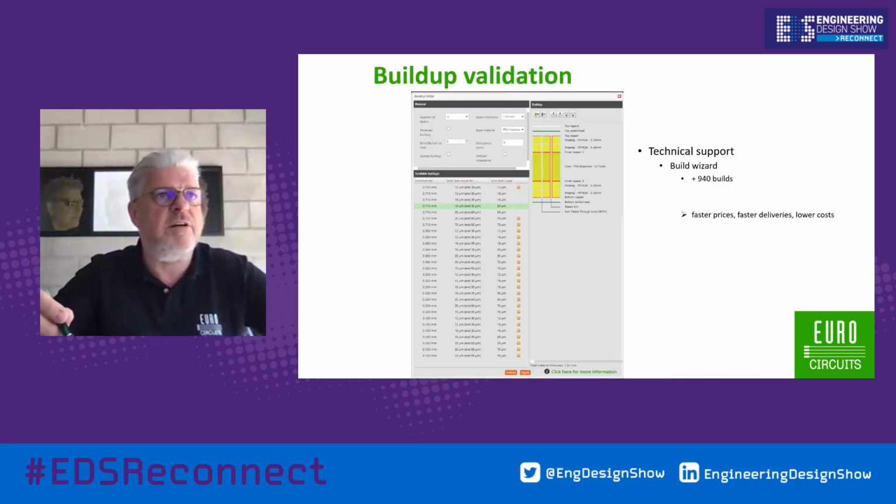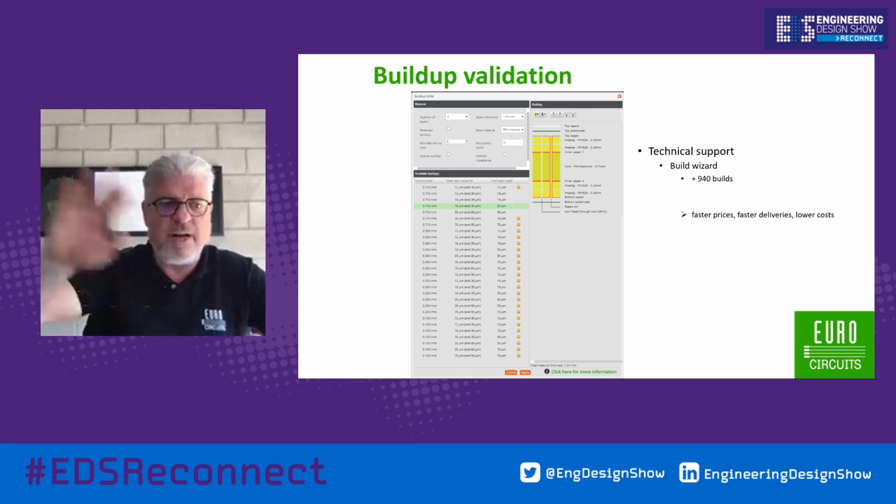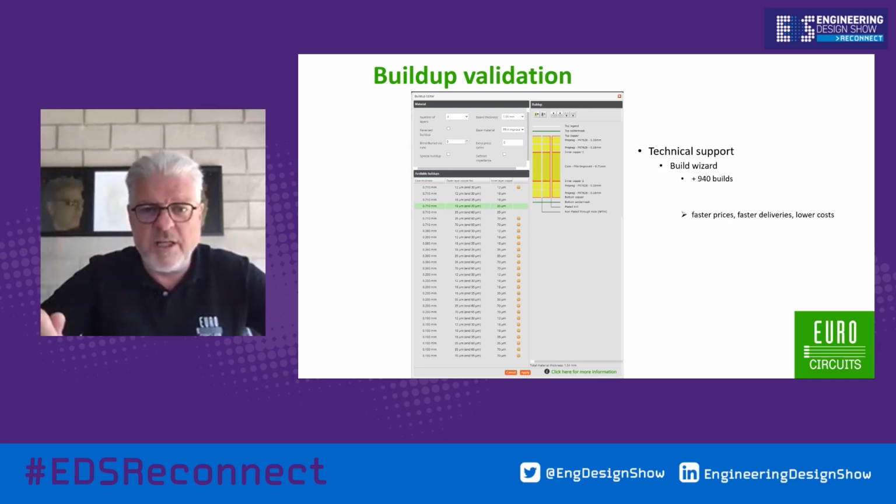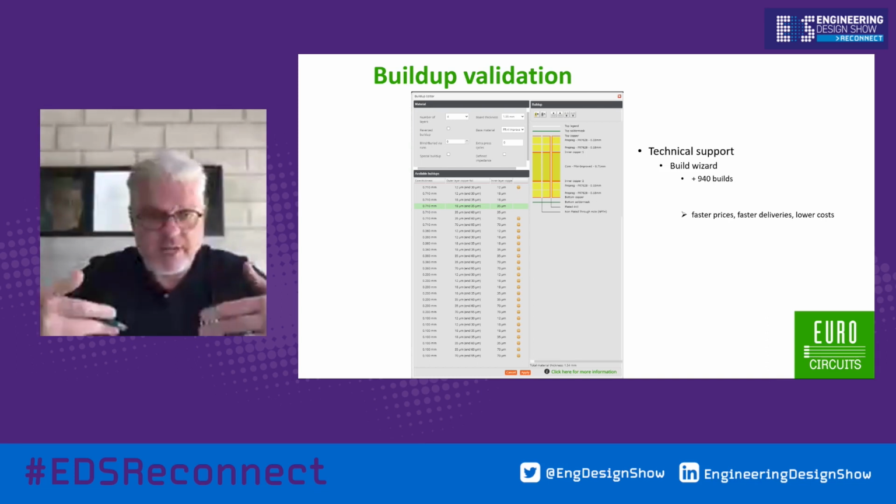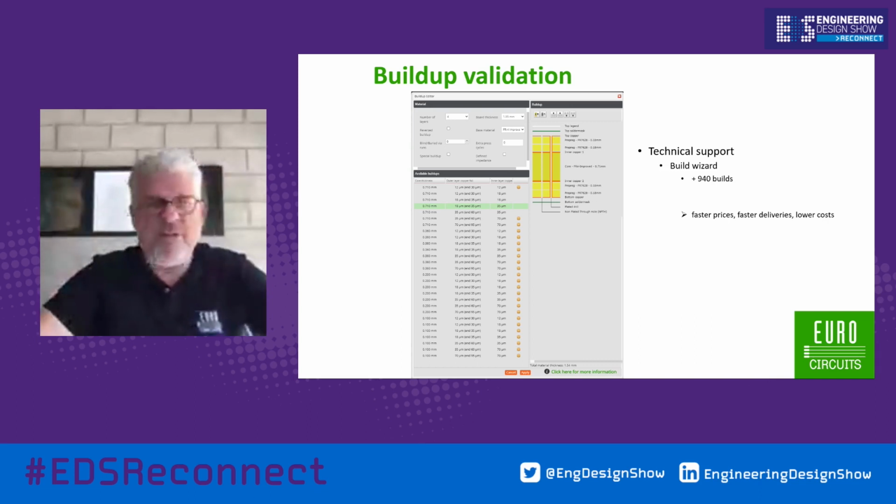To give you a nice example is build-up. Build-up or stack-up is one of the most critical things to choose from. If you start building your own stack-up to your own liking, from what you can find on the internet for materials, then you're not sure if they are available, if your manufacturer likes to work with them, how long it will take for your manufacturer to get them in stock, and so on. So all of these rules about build-ups, stack-ups that we have in-house and the materials that we have in stock, it's in the build-up editor.